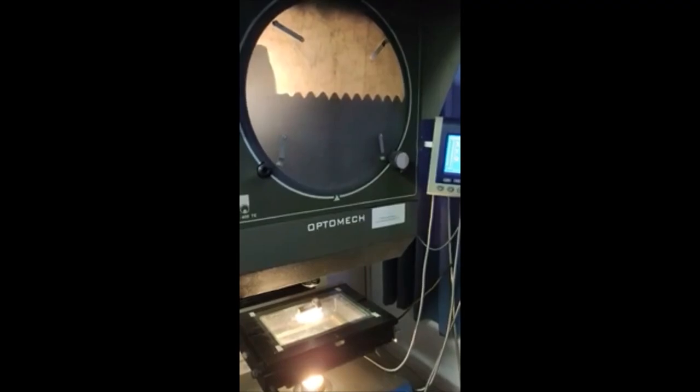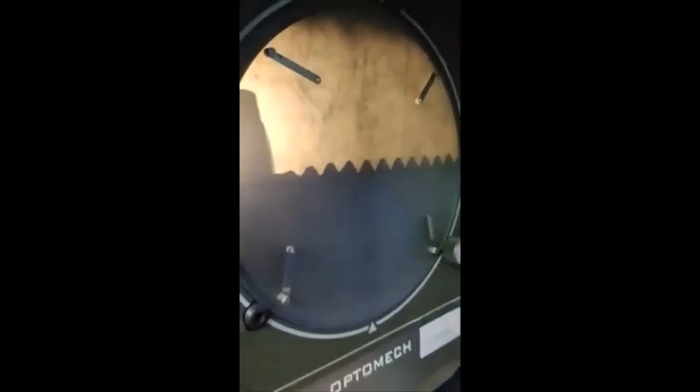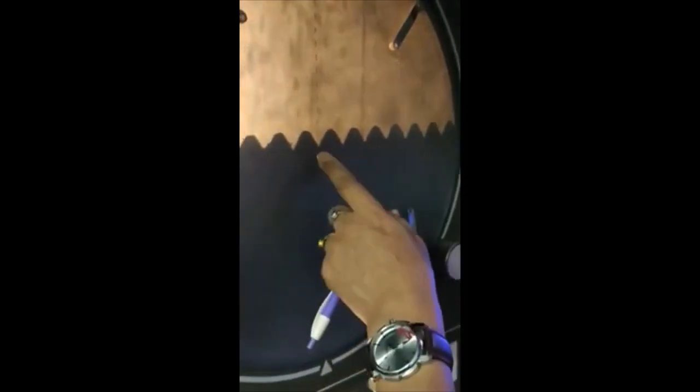Now let us come to the thread pitch measurement of a bolt with the help of this profile projector. I have taken one bolt and I will measure the pitch of this thread and the thread angle of this threaded bolt. I have placed it here, and this thread profile has come here. After seeing this thread profile, I will adjust it like this. Suppose I want to measure the pitch. Suppose this is crest to crest, that means the center of the crest.